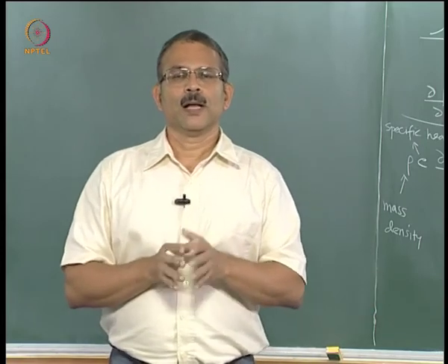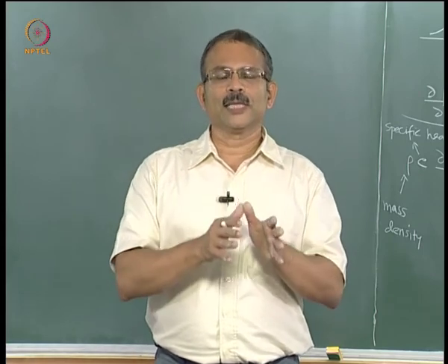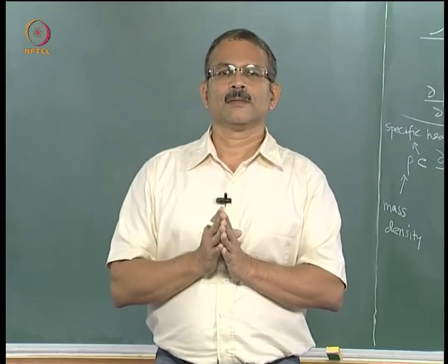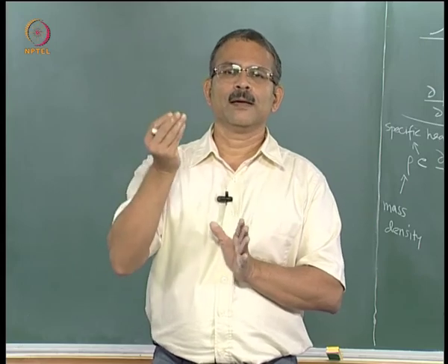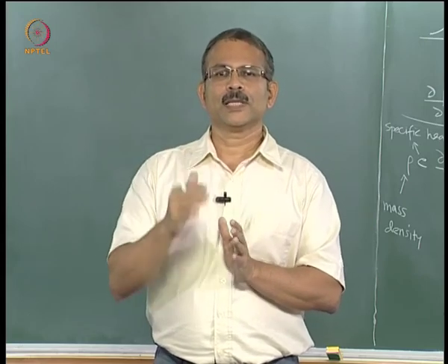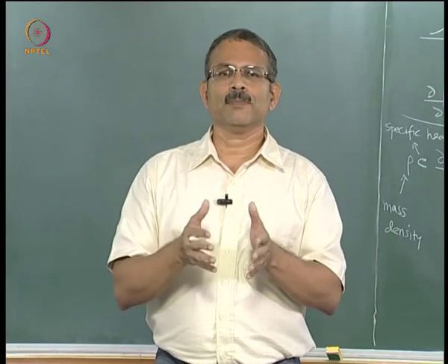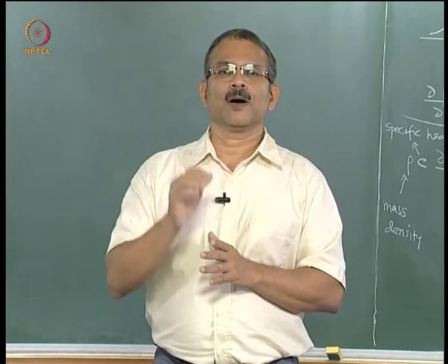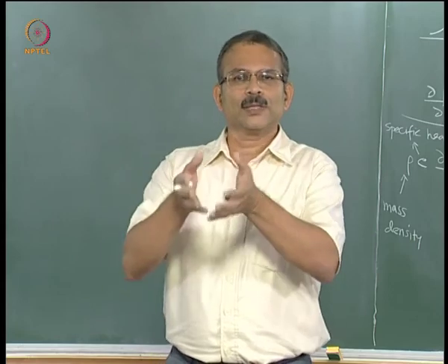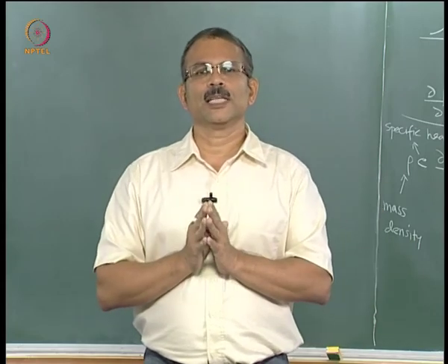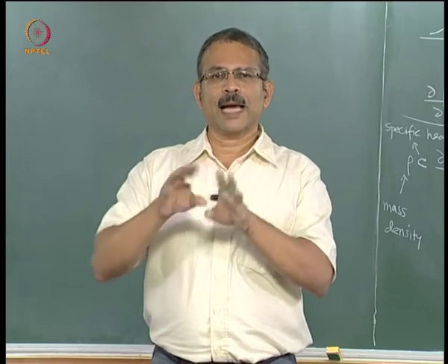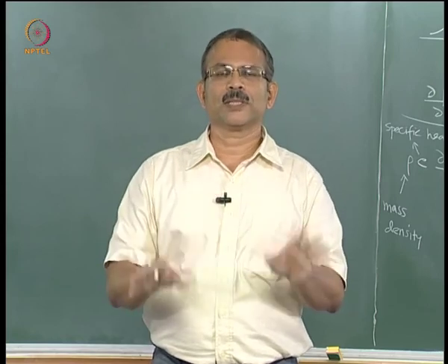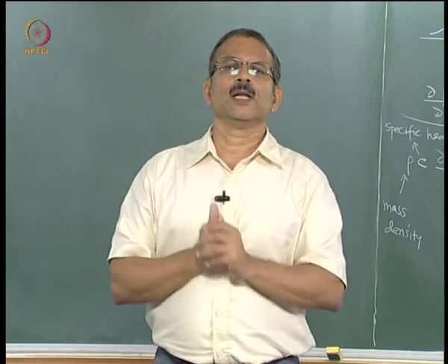It is a solution. Then we said that you can use this equilibrium function and modify it by making it a displaced Maxwellian function by introducing the directed velocity term in the equation, which is the sign of non-equilibrium. In equilibrium there is no directed velocity or no momentum. In non-equilibrium you have a net momentum or a directed velocity. So we introduced this term. The resulting function was called displaced Maxwellian, and we said by modifying the carrier temperature and using this directed velocity we can modify this distribution function under equilibrium sufficiently to manage the non-equilibrium conditions.